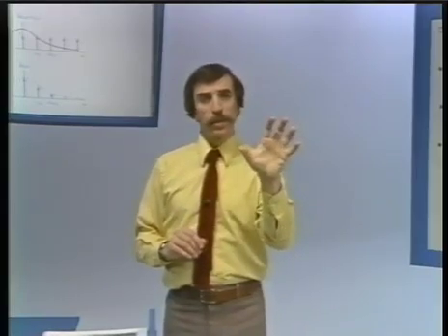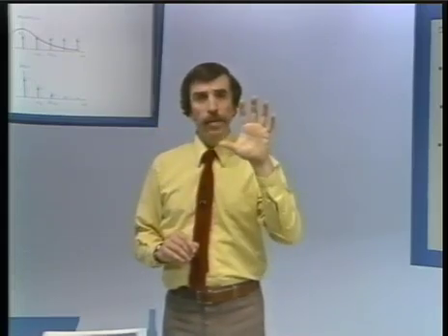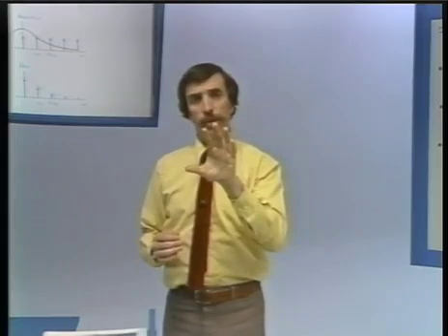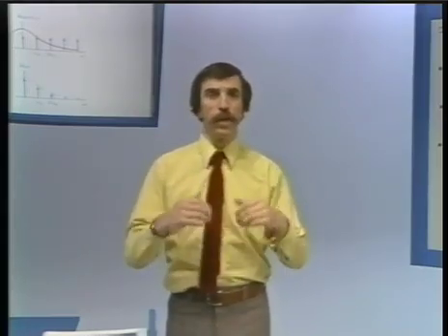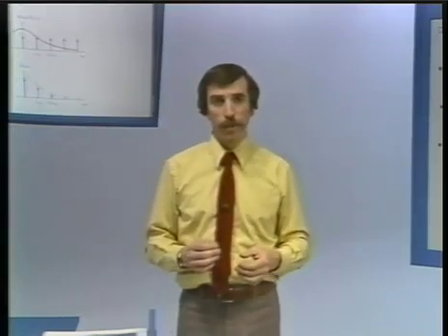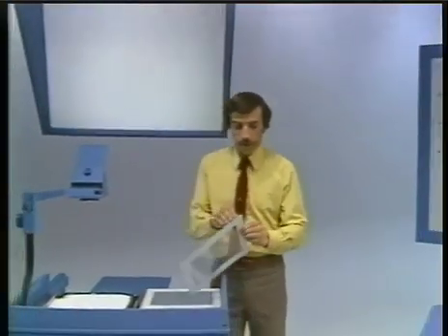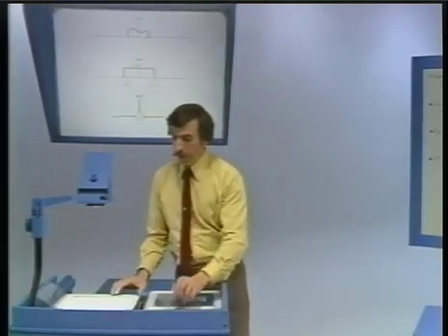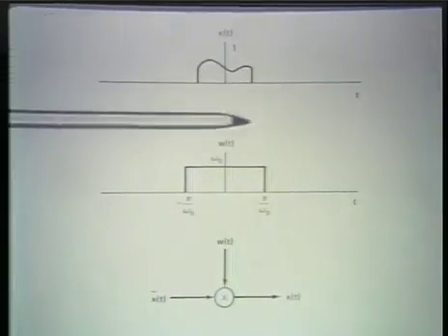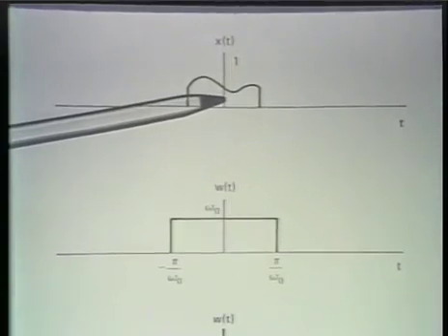Namely, the time domain signal is replicated at integer amounts of a particular time associated with the spacing in frequency under which we're doing the frequency domain sampling. So, in fact, if we look at this in the time domain, the resulting picture corresponds to an original signal whose spectrum or Fourier transform we've sampled.